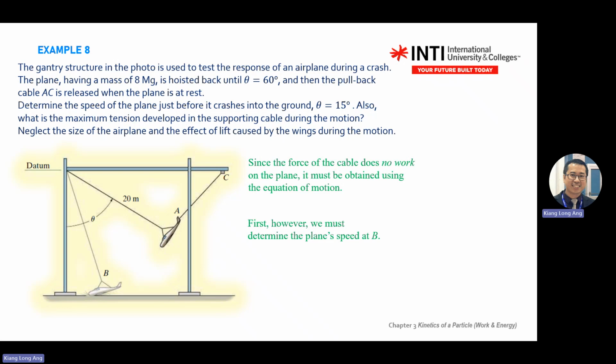What is the work definition? Work equals force multiplied by distance. They must be parallel. In what case is there no work? When your force and displacement are perpendicular, there's no work. If you are the aircraft, this is the cable, you always tie perpendicular to the displacement. So no work. So if no work, then you can use the equation of motion, F equals ma.